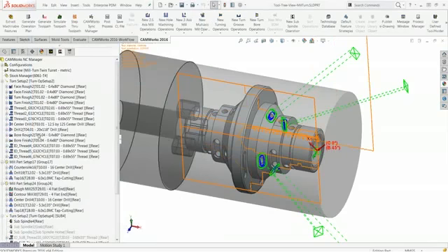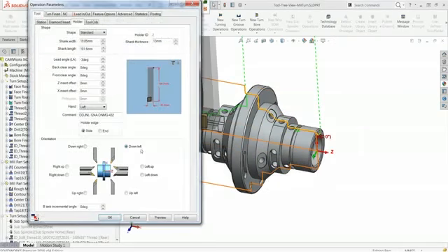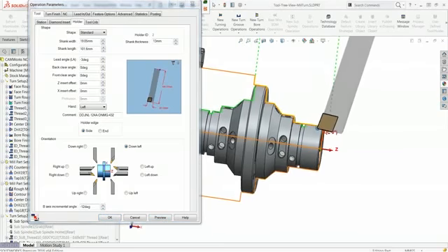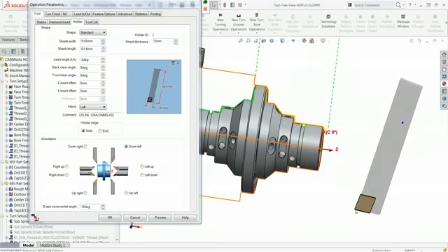And speaking of turning, if we go into one of our turning toolpaths, so we'll just edit the definition on that turn tool, you'll actually see we now have a B-axis incremental angle under the holder settings. So again, as long as your machine can handle the B-axis, we can actually tilt that tool. And then you'll actually see the tool being tilted right on the screen too, so you can see whether that's going to match up and cut that the way you want it to be cut.